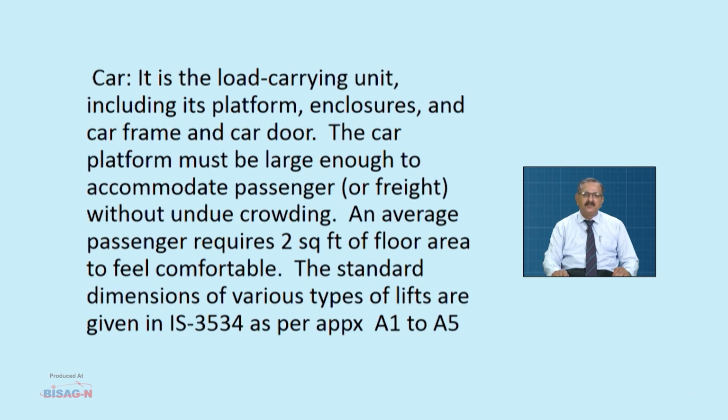Car. It is a load carrying point including its platform, enclosures, car frame and car door. The car platform must be large enough to accommodate passengers or freight without undue crowding. An average passenger requires 2 square feet of floor area to feel comfortable. The standard dimensions of various types of lifts are given in IS 14665 as per Appendix A1 to A5.